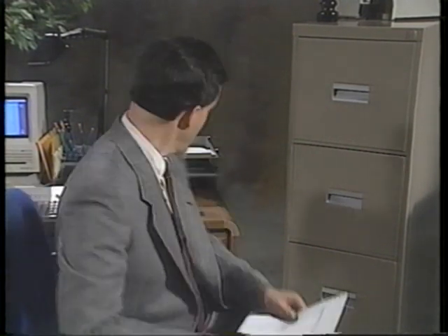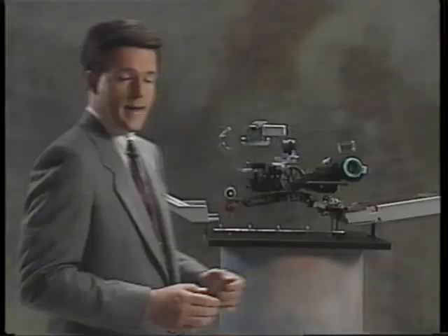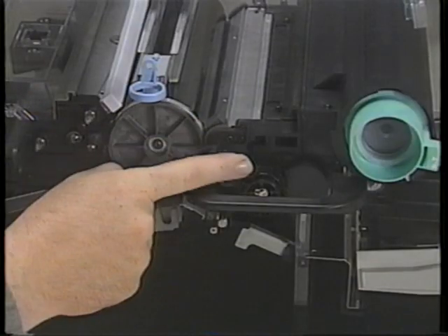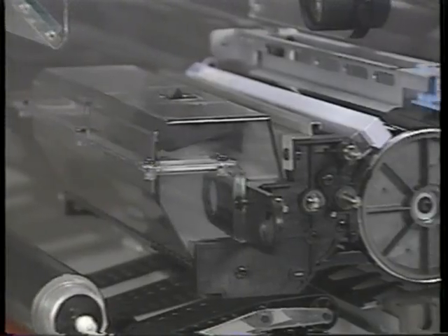In a copier, development relies on electrical attraction and magnetism. As the latent image moves away from the exposed area, for the first time in the copy cycle, the photoconductor comes into physical contact with another component, the development unit here. Now remember, the latent image is actually a pattern of electrical charge. That's what makes the development process possible.